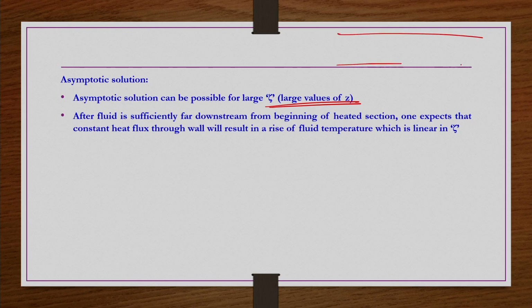So, let us say this is the pipe. Okay. So, now we are far away from the inlet and outlet, where the velocity profile is fully developed, right, and then we are having some parabolic profile like this. So, in this region what happens? Whatever the variation in the velocity is not there. So, variations in the velocity in the flow direction are 0 in the fully developed region, isn't it? So, that means the relative motion between the wall and the fluid regions is going to be the same.